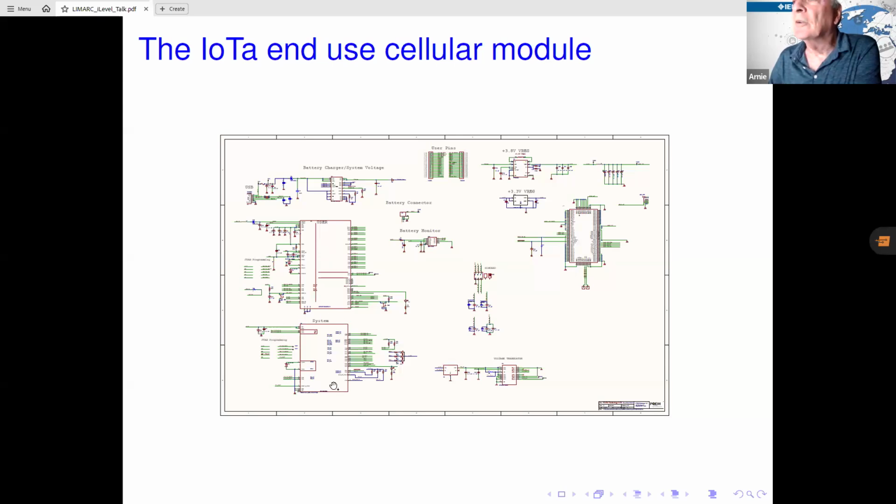This is the system processor. The reason for these 2 separated functions is that the system processor controls all of the modem commands, the AT commands that drive the whole session. So you don't want your program, which in our design you can program with an Arduino programming interface, to screw up the modem and brick it. And that's why the 2 are separated.